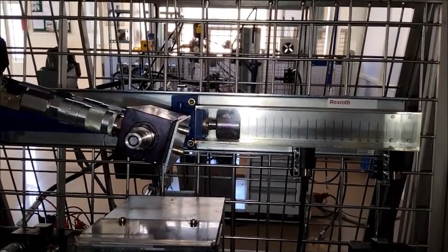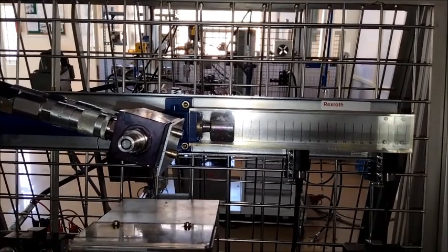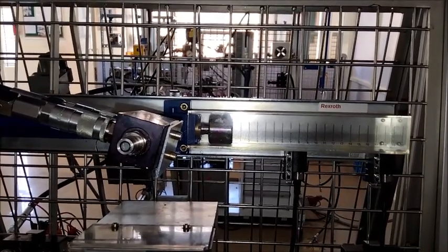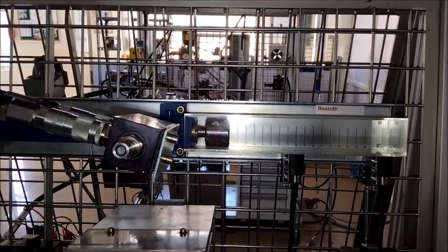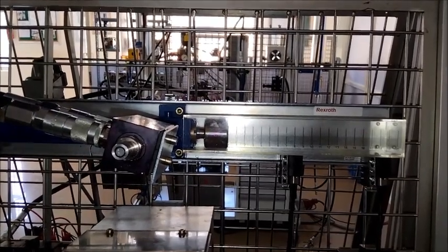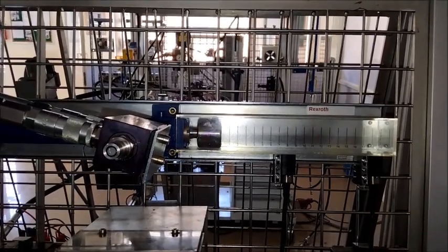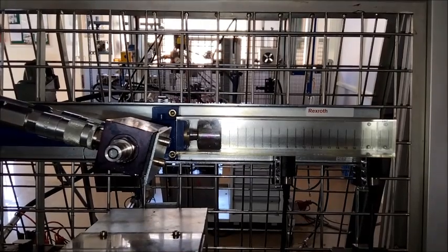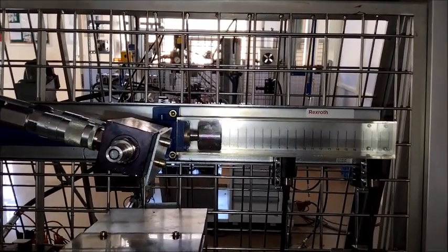The tool bit should approach the workpiece at a faster pace, but when it is performing a cutting operation, the speed of movement of the tool should be less, because otherwise the tool bit is going to break. So we are talking about the feed given by the hydraulic cylinder. The spindle is driven by an electrical motor, but the feed can be given by the hydraulic cylinder.